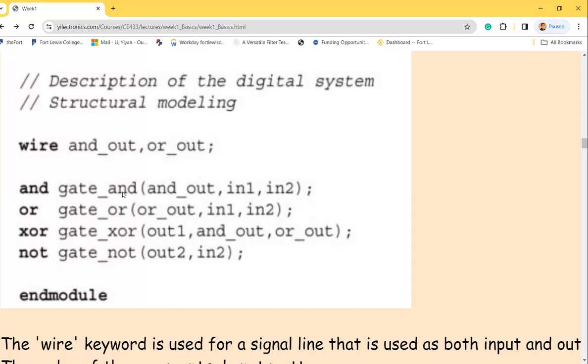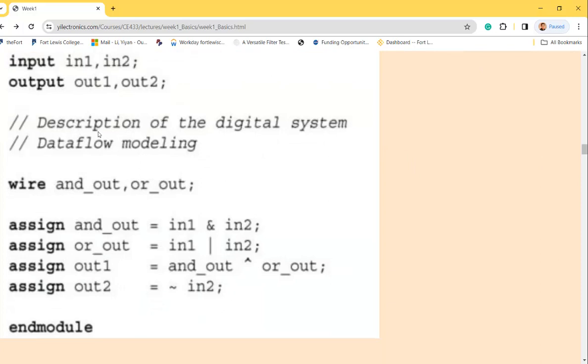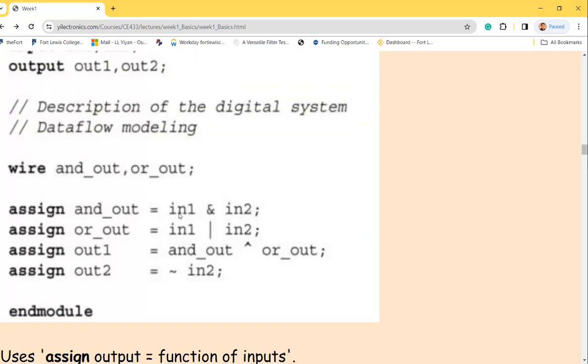So this is the name you give to it, okay? It can be something else. But this will define a certain logical operation here. The two following at the end are the inputs, and this is the output. And this is the name of the gate. And this gate is doing an AND logic. That's the structural modeling method. And the data flow modeling method is you have ports and logic operators, you assign to something and use the assign keyword in here. So assign is a one-liner, okay?